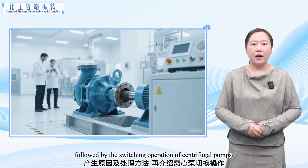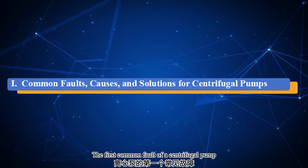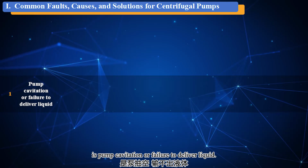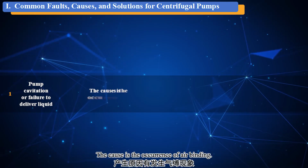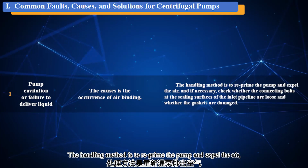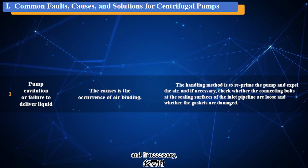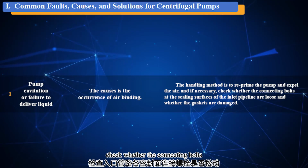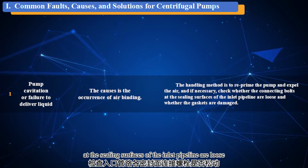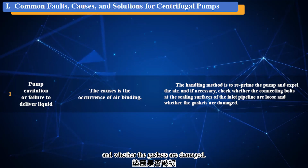of centrifugal pumps. The first common fault of a centrifugal pump is pump cavitation or failure to deliver liquid. The cause is the occurrence of air binding. The handling method is to reprime the pump and expel the air, and if necessary, check whether the connecting bolts at the sealing surfaces of the inlet pipeline are loose, and whether the gaskets are damaged.